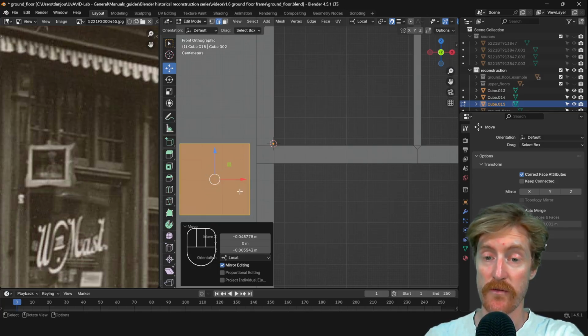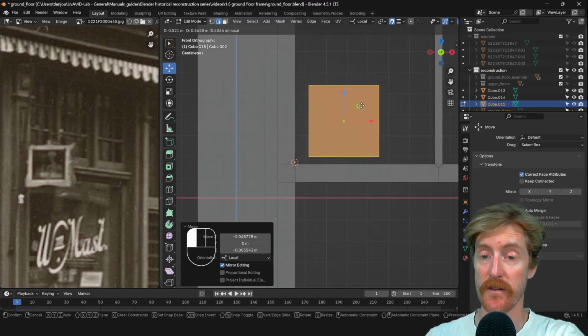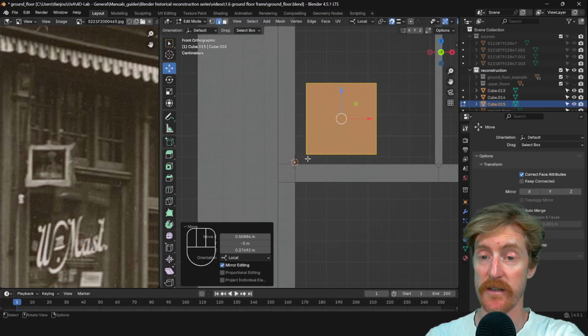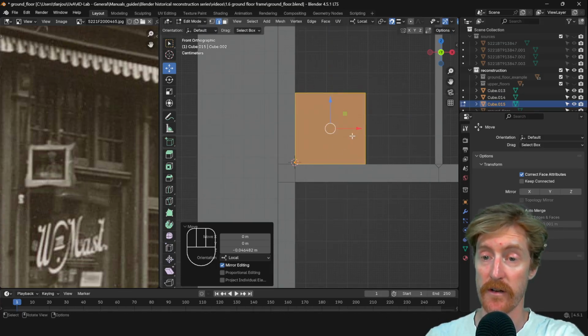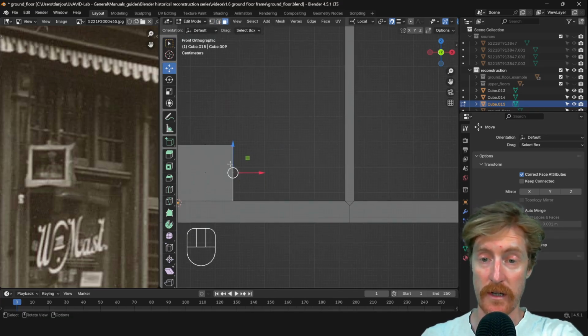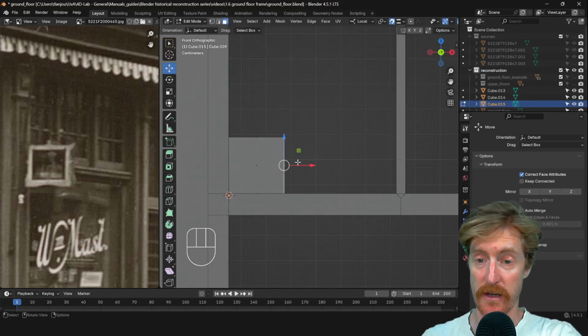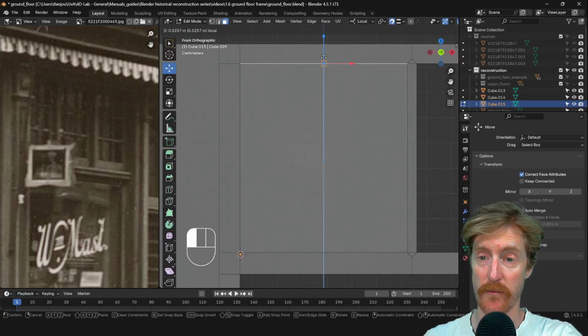So when I want to snap this side, this corner, or these edges to these edges, I first have to move it to the inside to make sure that these edges are the closest to these edges. So now I can move it to the side and also move it here, and it is snapped to the outer frame. Now we'll make sure that I have face selection mode on and select those and move it.